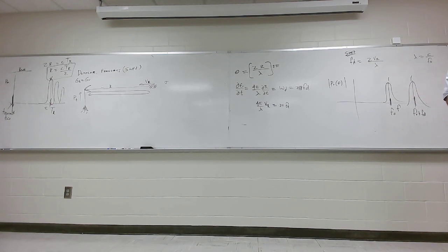It's how far out a target can be, or what's the maximum possible range we can see a target and know it's actually at that range without being ambiguous. Remember I said the problem of sending one pulse and a second pulse before the first echo is received? You don't know which one? So there's a thing called the maximum unambiguous range, and then there's a thing called range resolution.